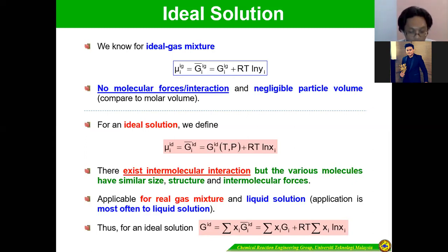In that chapter we determine the fugacity of the gas phase, using the fugacity coefficient. But in chapter 5, we mostly focus on the solution or liquid. We have to determine the fugacity of the liquid based on the activity coefficient. The symbol is gamma. Since in equilibrium, the fugacity in vapor and liquid is similar.